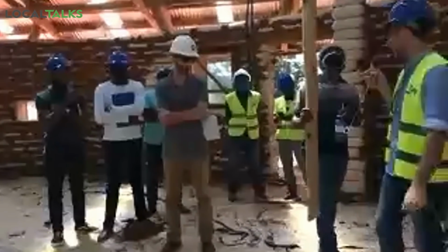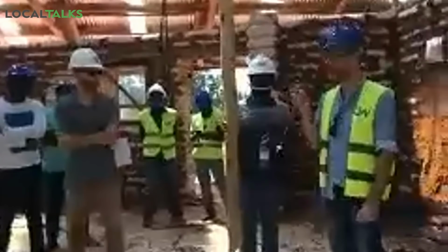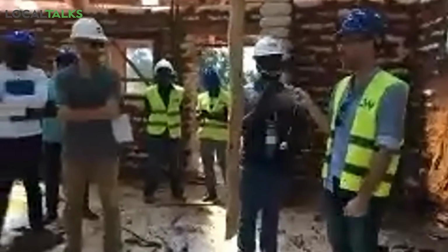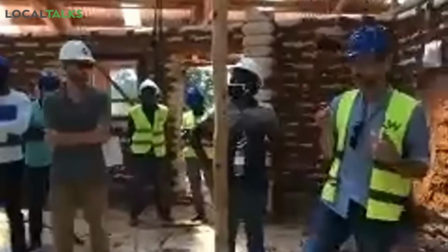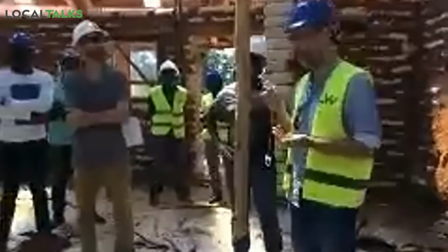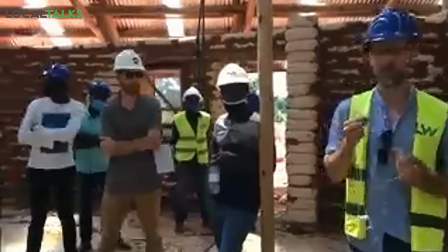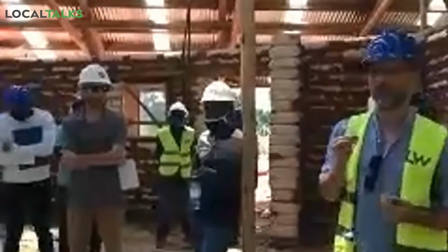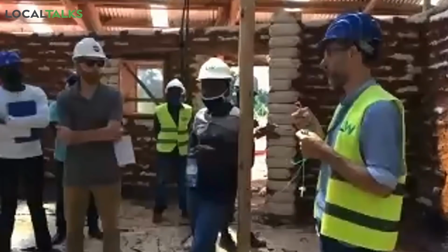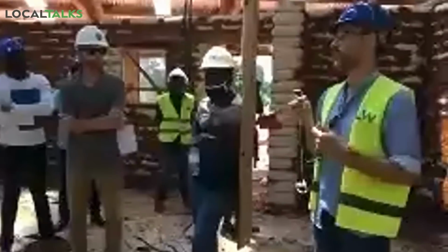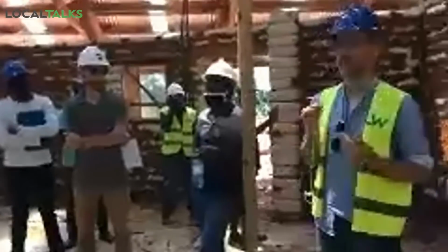And how are we treating them? How are we treating the makoko? No, we are not treating it at all. The property or the whole quality about wood is that there's not really a big problem with wood getting wet. Wood is quite good at getting wet. What is not good is if it can't dry. Now, if you install it in a way that there's air all around, especially in the case where it is exposed to the sun like a roof is, it will not actually rot that fast.